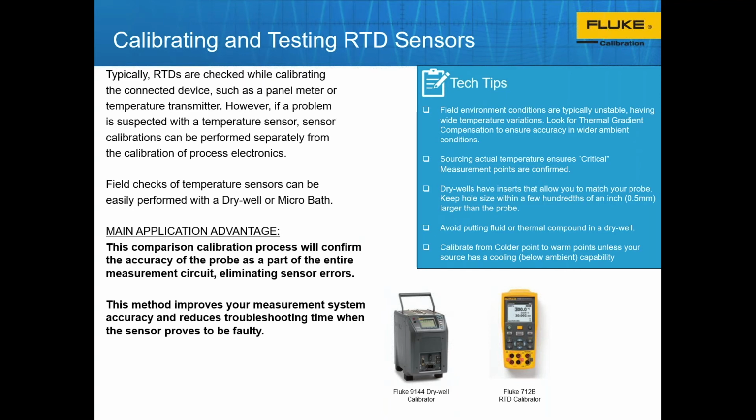A tech tip we can suggest is, because temperature sourcing takes a long time to heat up and stabilize and become the same temperature, and you have temperature uniformity between the probe that's in there and the sensor that we're using to control everything, maybe even a secondary probe. Once all that becomes stabilized, that may take the better part of anywhere between 10 to 25 minutes. And if you had multiple temperatures to change, that's just adding time to your entire calibration, which is just a function of how things happen.